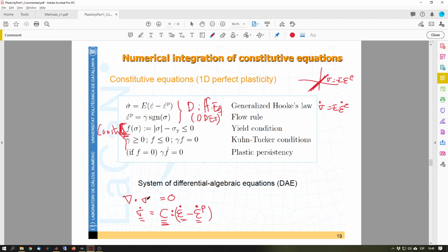Okay, this is Cauchy's law, that it's always true: linear, nonlinear, plastic, damage, etc. And we have this constitutive law in that case, and in addition we need to specify how my strain rates are related to the stress. So we have a constraint that now is a function that goes from R to R in that case.